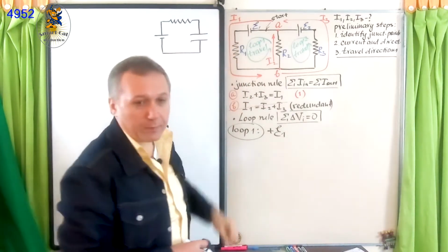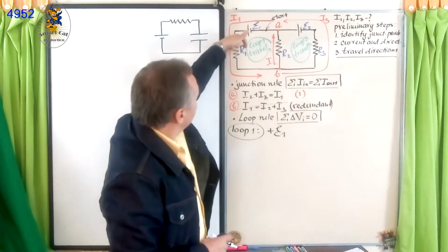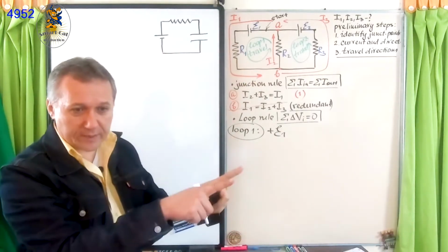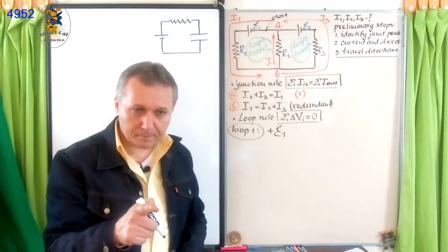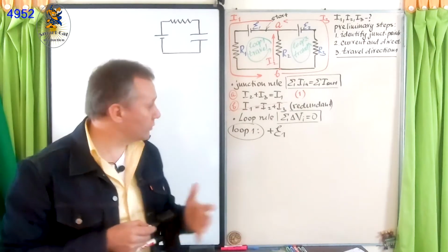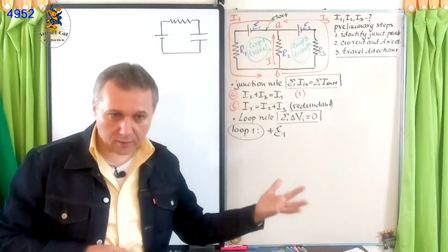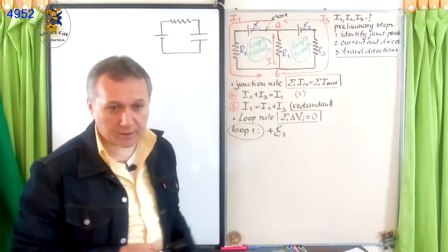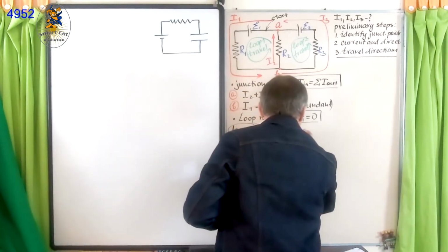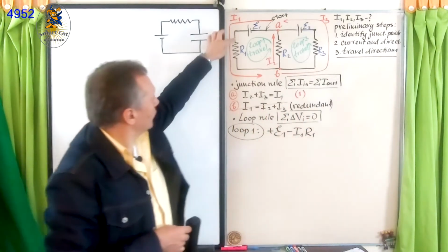Now after this, we're up against this resistor with resistance R1. Okay, so travel direction, you see, down. Current direction also down. So directions are the same. Rule number 3, if directions are the same, if you're dealing with a resistor, contribution to the loop equation is negative, and the value of that contribution is IR. In this case, current I1, resistor R1. So minus I1 R1.